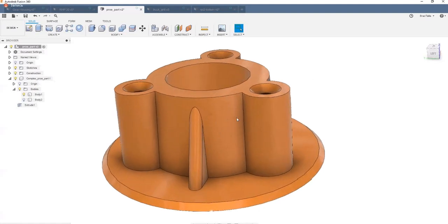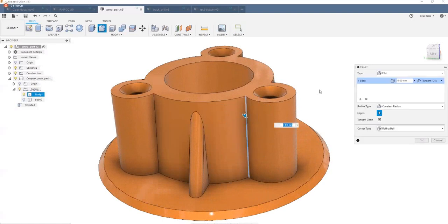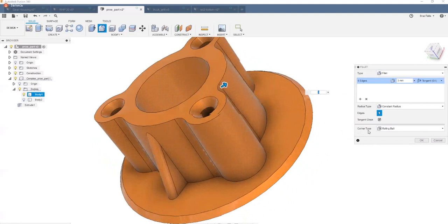Now I can come back and start recreating. For example, I'm going to select that edge and say fillet. Now, I always forget to do this. I typically make a copy of the original model, and then I can reference that. I'll maybe have it over to the side and say, what size is this fillet? Oh, it's 3 or whatever. But I've done this demo so many times, I already know that these are radius of 3. So I'm just going to go around and pick these edges to create a nice radius of 3 all the way around.